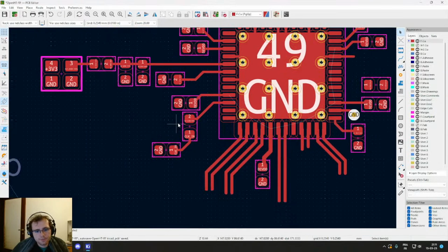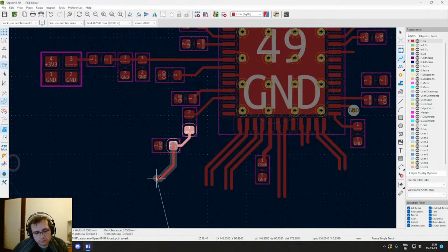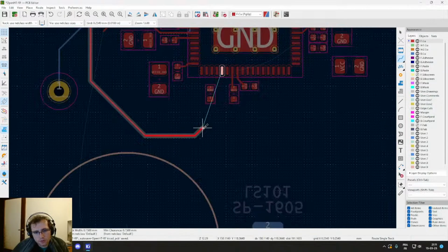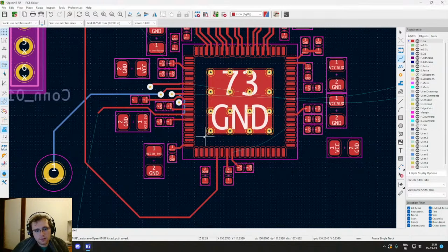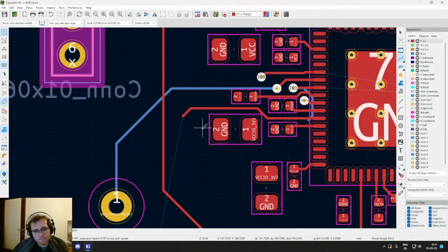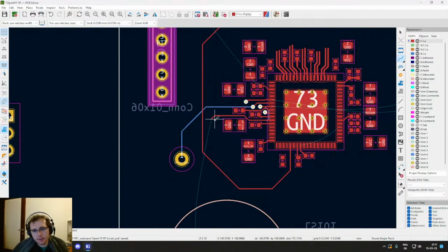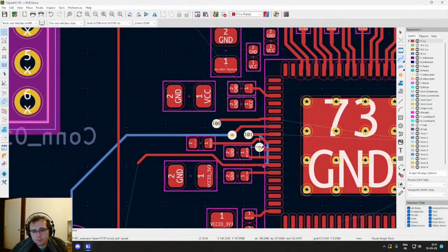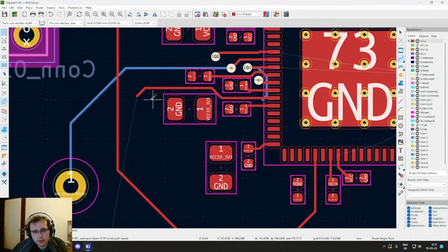Okay, first the clock. I guess we can just roughly like this. Should be good. So yeah, this one, if it's far enough from the FPGA, it's not going to have power plane trouble, so it's going to be able to be routed properly with a good reference plane below.